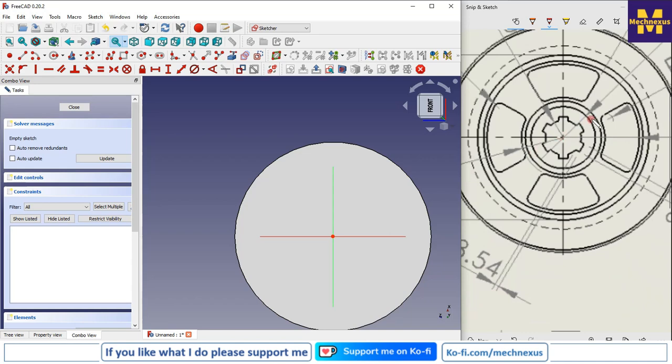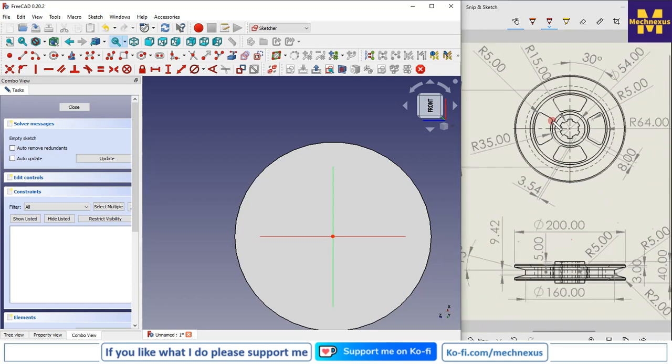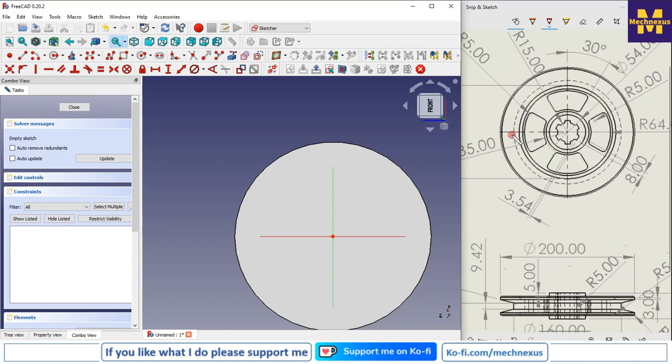So this diameter is 54. So I will select the circle and give it a diameter of 54.